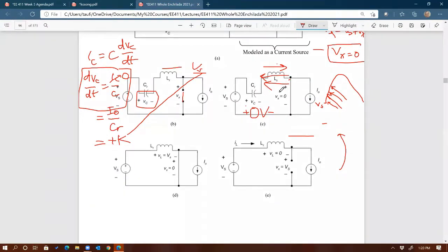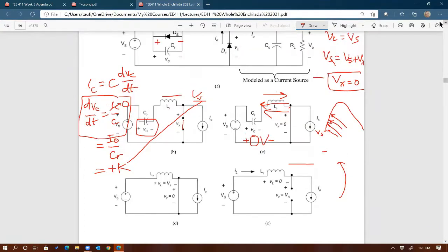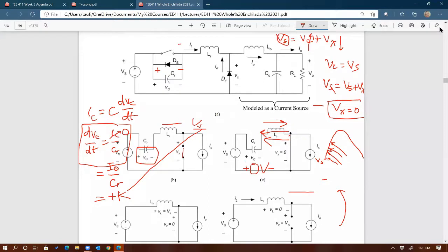But that negative current cannot flow through the capacitor anymore. You agree? Because there's no more charge left in that capacitor. So where does that negative current flow? The diode, yes. So that's what's wonderful about this, and it's almost like magic. To this day, I'm still amazed with how the circuit works.